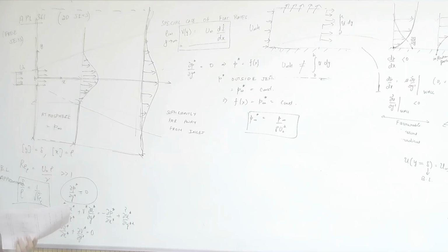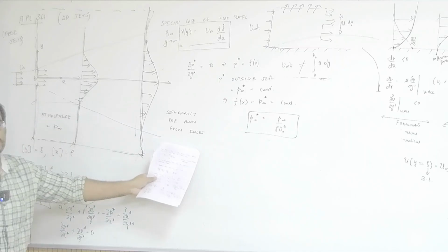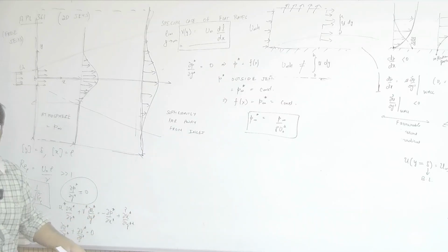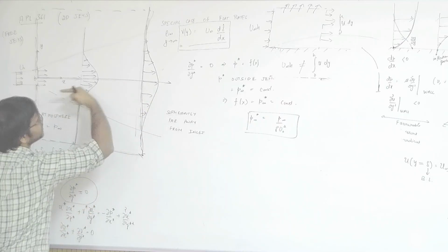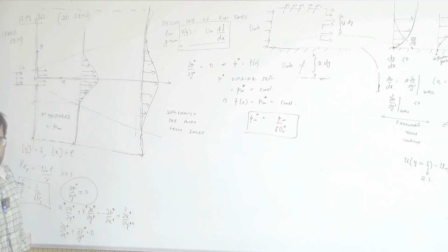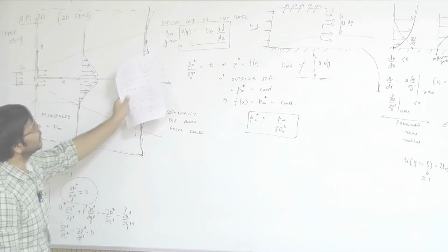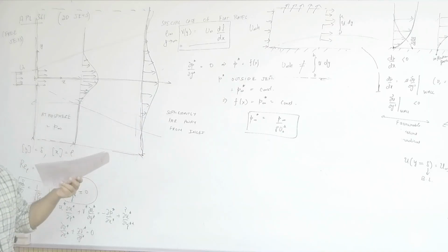That is a very high pressure thing that is coming, and you have to move sufficiently far away from that orifice to reach this region. And even then we are going to look at laminar jets. In that case you don't have a laminar jet, plus there is gravity which is acting in this direction in that particular case. So this is a very non-intuitive application of boundary layer theory, but nonetheless it works.